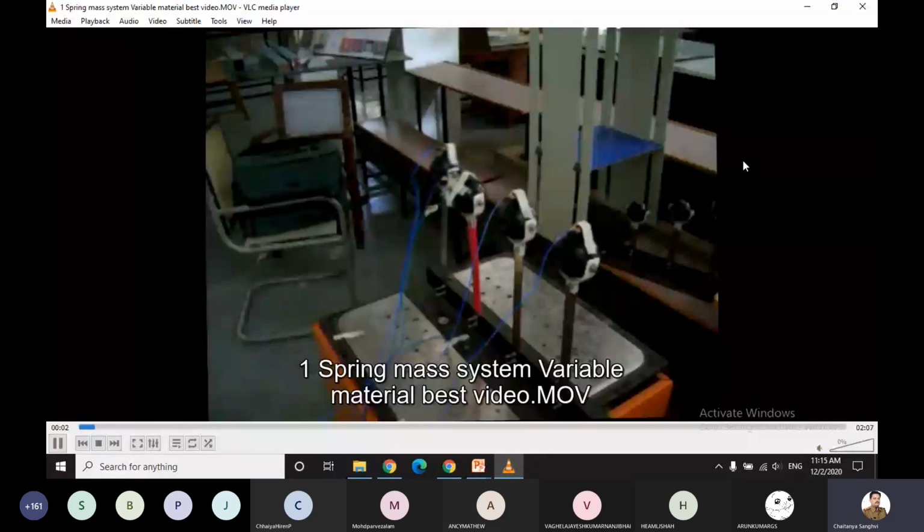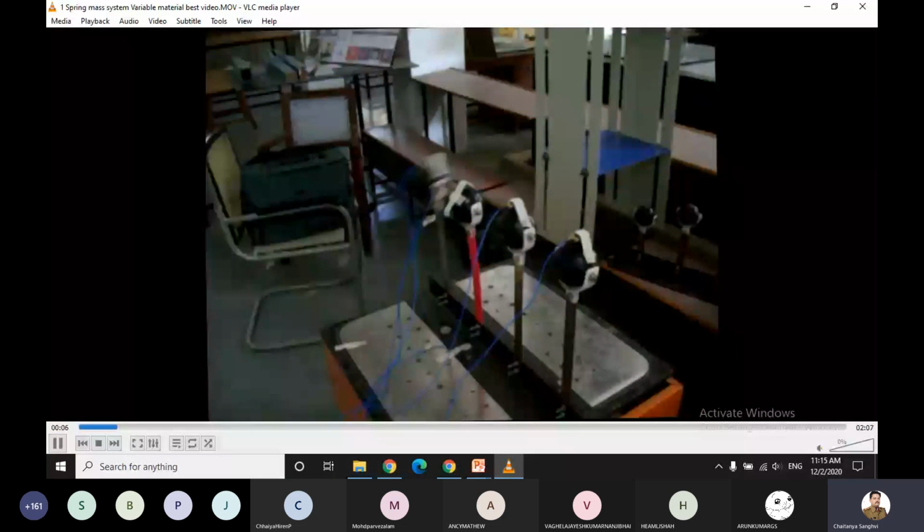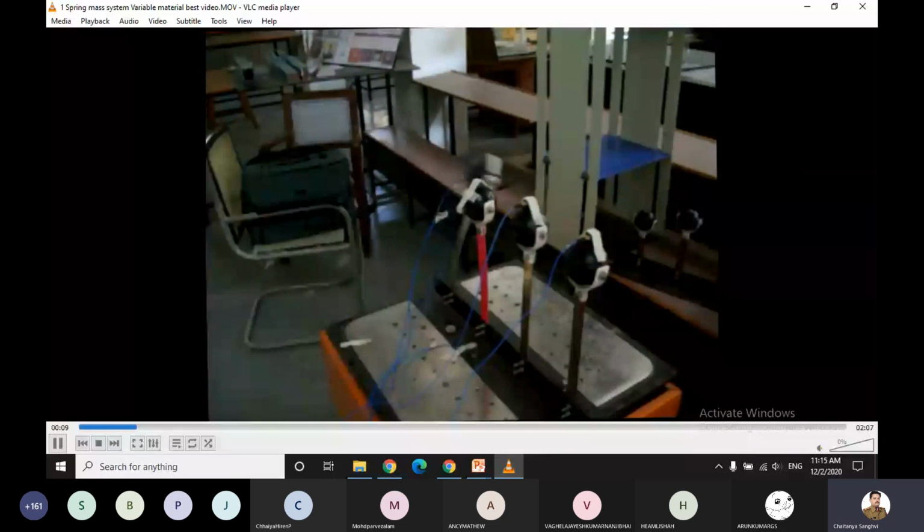Again, you see here, you have to observe this experiment again, because this is very important from the resonance point of view, and you cannot say my steel structures are affected or my RCC structure will be affected due to this. Again, it depends on the frequency carried by the earthquake and the frequency of your structure. If both match, then a larger response of your structure will be there, right?